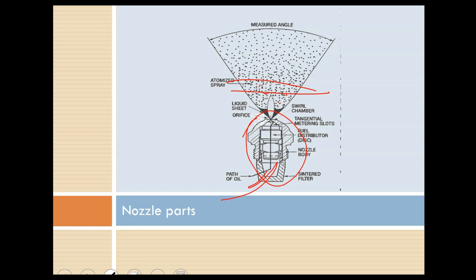And there's a lot of research and engineering that goes into putting together a properly assembled nozzle. So it's a good idea to not change the geometry of the nozzle, and also not to drop it. You see this little space is very tight, so if you drop a nozzle, you probably have to change it. And you can see how overheating will ruin the nozzle, and also the orifice size change will cause the nozzle to malfunction.